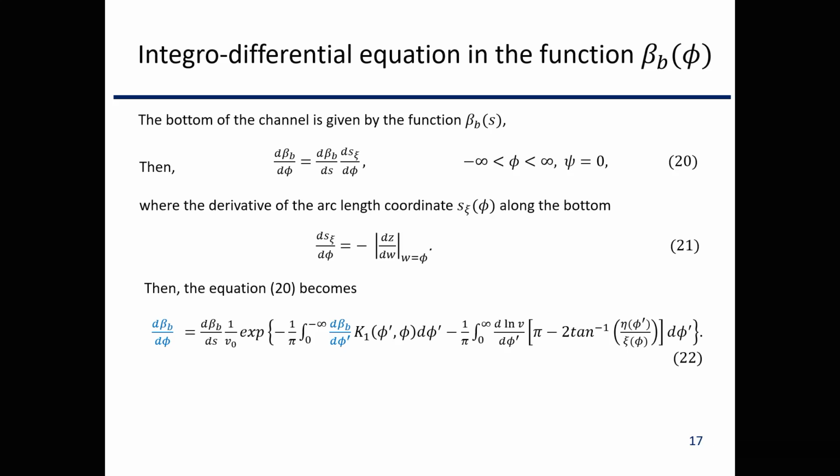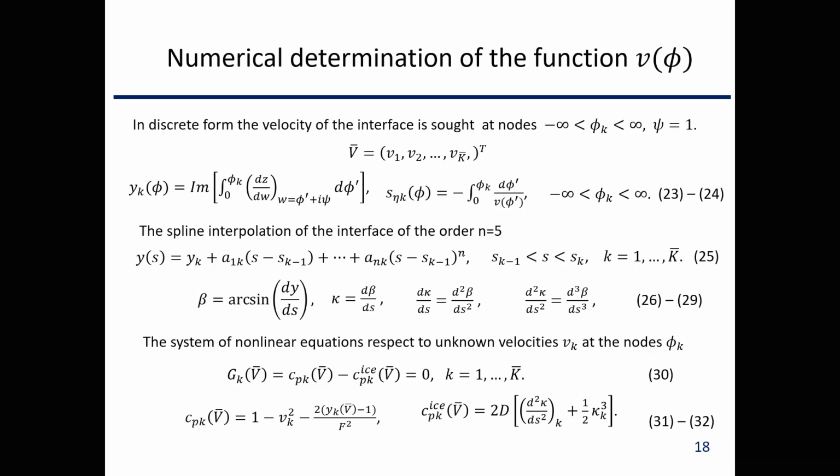Next slide, please. Okay, I already described it. This is what I told about the numerical solution of the dynamic boundary condition. So you can see that the equation for the pressure contains the second derivative of the curvature, and it represents some significant numerical difficulties and requires higher order approximation of the interface. Next slide, please.